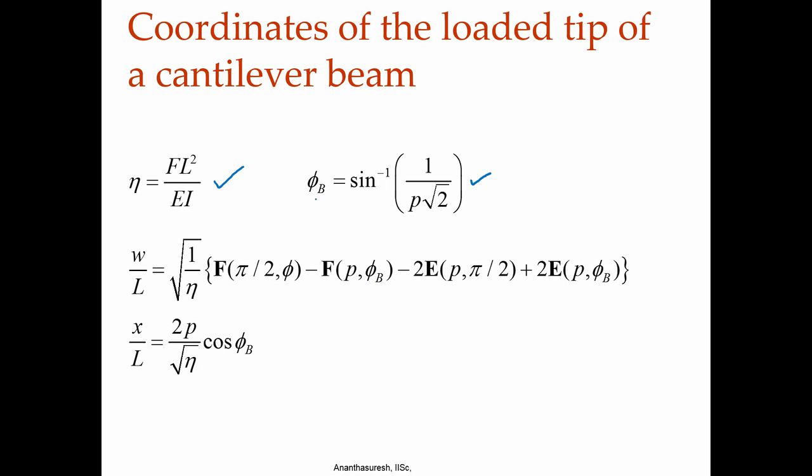That is the change of variable corresponding to theta equal to 0, where the cantilever beam is fixed. When the beam is like this, the point is what we call b, that is why I am calling it phi b rather than phi 0. Phi 0 is when this bends like this, when we extend it over there, this is where phi is equal to 0, and here phi is equal to pi by 2, if you recall.